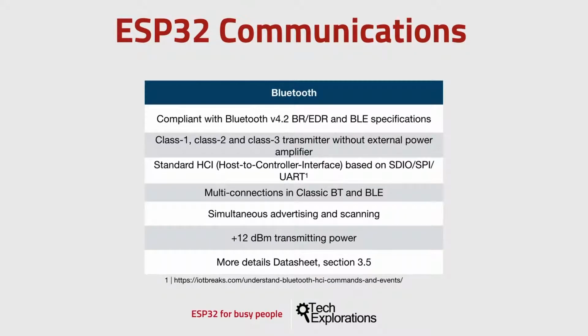As far as the Bluetooth capability is concerned, the ESP32 is compliant with classic Bluetooth 4.2 and BLE, Bluetooth Low Energy specifications. It contains a class 1, 2, and 3 transmitter, and it can simultaneously advertise and scan. And again, more details in the datasheet.